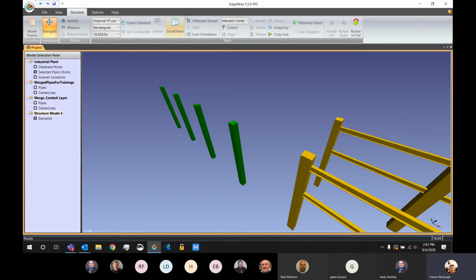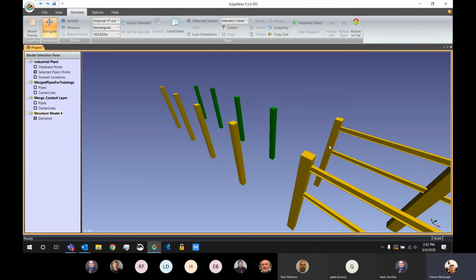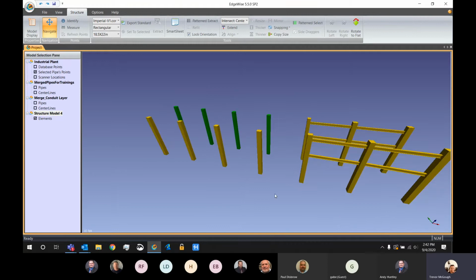So as I continually do these sweeps, I can go ahead and pattern over to the left. Now that I've done that, I can grab my concrete beams and then pattern them over to the right. And by doing this almost printer head approach, this quickly allows me to build up my different elements, and that way I can do multiple sweeps and basically knock out my whole truss.